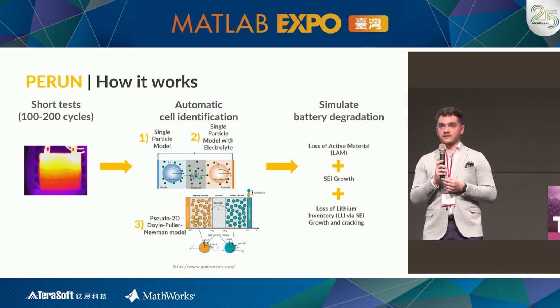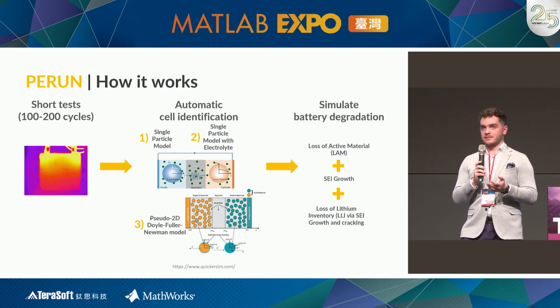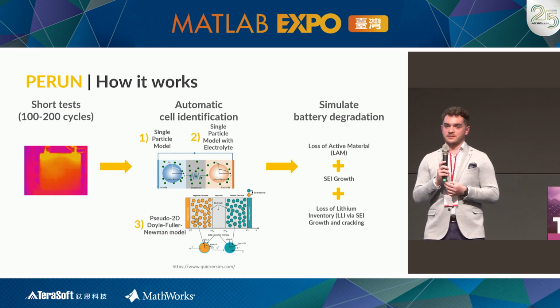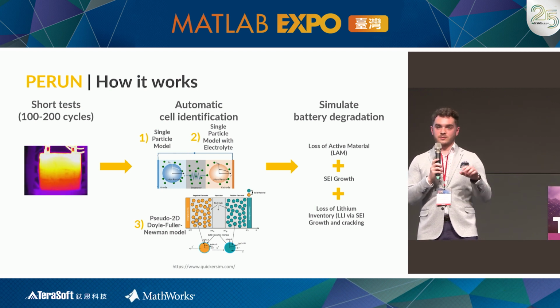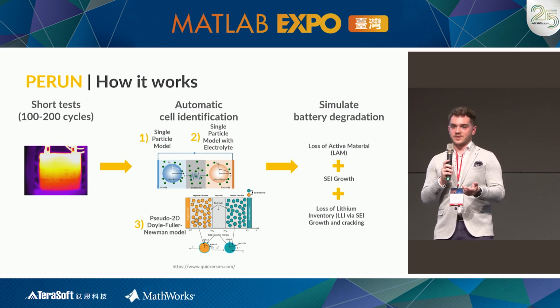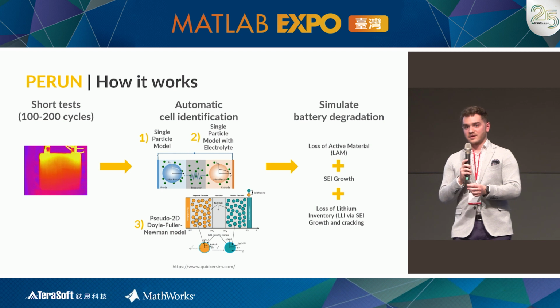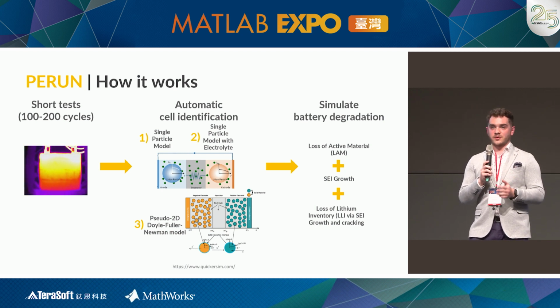They simulated that with a different company which used ANSYS Fluent. To simulate a battery pack with 200 battery cells inside for just 1 minute, they had to first simulate a couple of battery cells, then make a simplified model of the smaller module, and then based on that make a simplified model of the entire battery pack. Those are 3 stages of simplification, and still the results were not very accurate because of the simplifications. It still took a lot of time just to simulate 1 or 2 minutes.